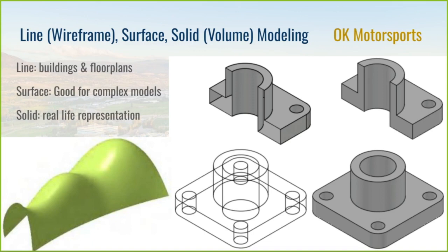But how do you get that block of wood? You can use a machine or a CNC router to make that shape using a program that goes down. Unlike 3D printing, where you're starting from the bottom up and adding, a router is subtractive, where you take a big block of something and start cutting it out. So you do a really big cut at the top, and you start going down, and you go down, and you go down. And eventually you have a shape like that.